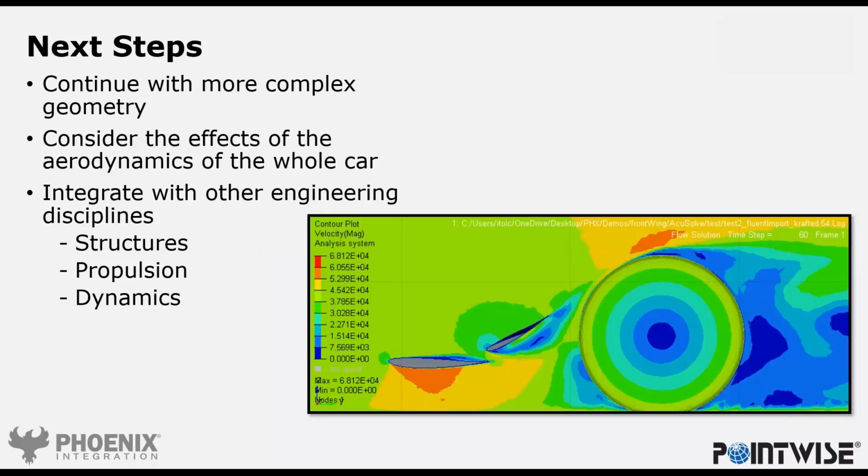The powerful thing about this method is that we start with a CATIA geometry, and the final result is the CATIA geometry. Often optimization is done on the mesh, and so at the end you have a modified mesh, but then you have a manual step of bringing that mesh back into CAD that can be manufactured, or it can be used as a starting point for analysis for other disciplines.